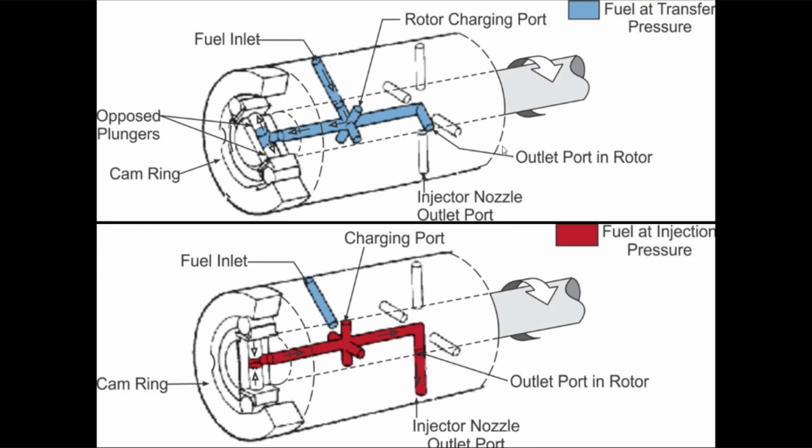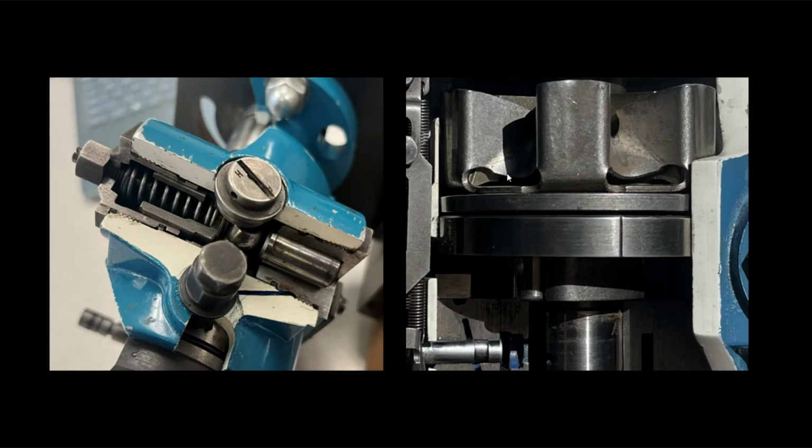The rotor continues to revolve in the hydraulic head, continuing the sequence of charge and discharge. One single revolution delivers fuel to all the cylinders in the firing order. Fuel takes a certain amount of time to ignite, regardless of RPM. Therefore, we need a system in place to adjust the timing to compensate.